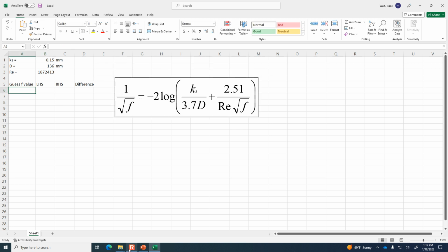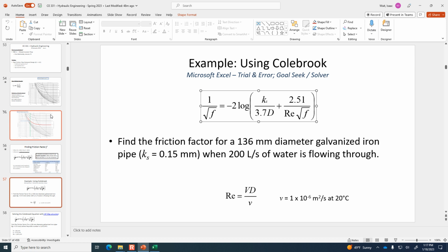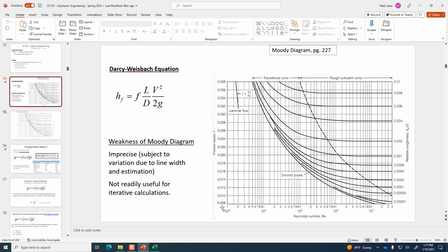Okay, so let's just check on the Moody diagram. What's the typical range? I know you had a homework problem where you calculated an f value of like, what was it, 0.9 or something, when you were finding the f value equivalent for this open channel. We don't use the Darcy-Weisbach equation for open channel flow much, so that was kind of an odd application.